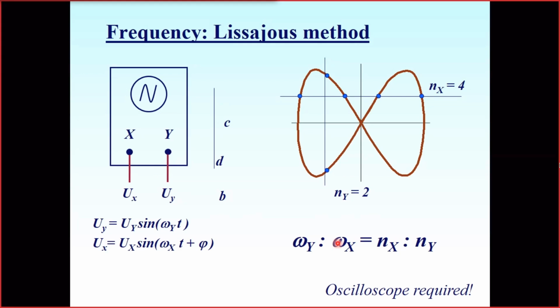I said the figure may use different ratios, but generally the measurement happens when we attach our reference generator and our source signal to the scope. We usually see just a colored rectangle, because there is no special relationship between the frequencies, and we don't see any figures.